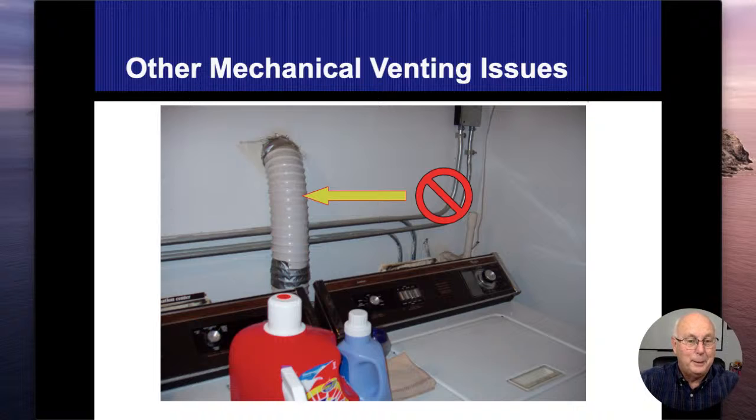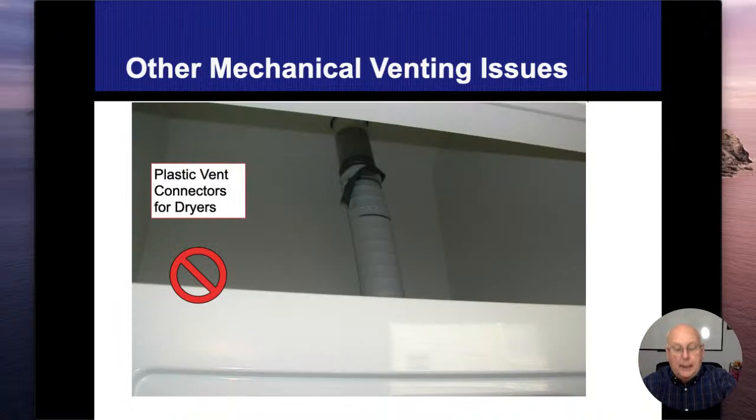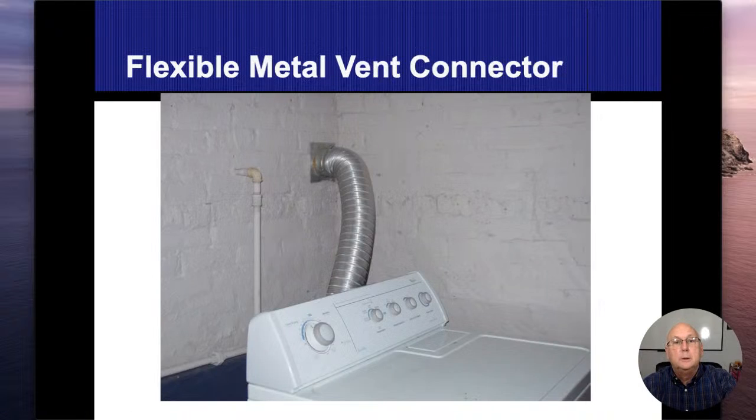I know this isn't really about heating, but again, different appliances, we vent them in different ways, and a dryer is an appliance. They do have different types of ducts that could be there. At no time are we allowed to use a plastic duct for a dryer. At least if it does exist, I am definitely not aware of it. All right, I've seen the soft foil types. I've seen the hard foil types. So these are the hard foil ones.